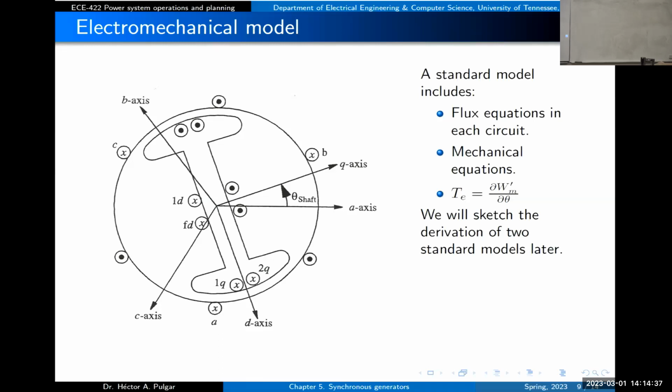Having this coil just in short circuit will help to damp any type of oscillation we might have in the machine. At the same time, we're going to have dampers also in this direction. These are along the direction of the flux, right? So any change of flux along the axis here in the rotor will create an induced current in the damper. But this one will require a change in the flux in this direction, because this is 90 degrees with respect to the direction of the flux. We're going to call this the Q axis, or the quadrature axis. That's the description so far.